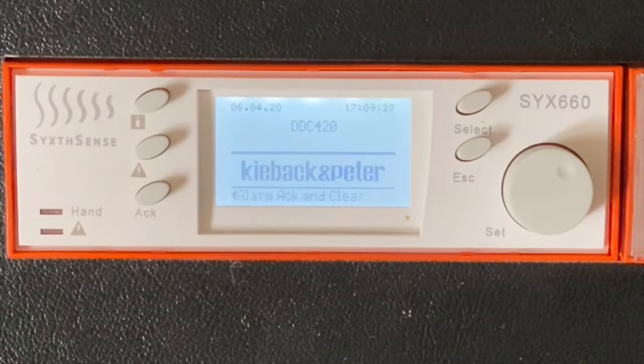During those summer months, it's the last time of the year where we actually want to have the heating running. So we have to find a way of making the plant work so we can actually test it. Having the commissioning mode is really handy because we don't have to over-manipulate the controller to make it operate, because a heating controller will fight us trying to make it run in summertime.